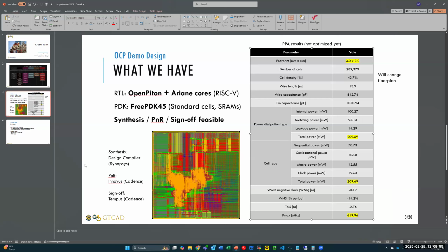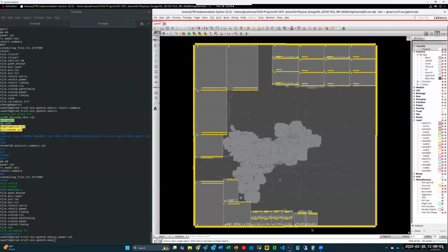The picture you were showing of the floor plan, is that the cell density? Is it mostly empty? Yeah, I haven't optimized the floor plan and macro placement for now, so I will fix this starting this week. The target utilization is about 0.7, so that the empty space will be reduced.